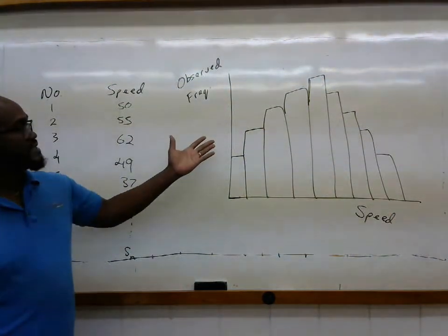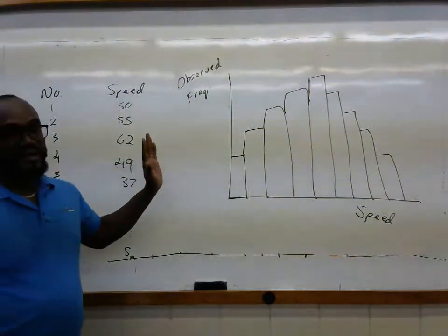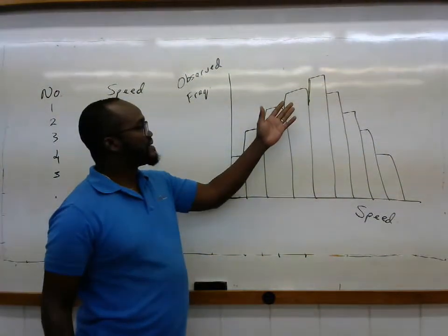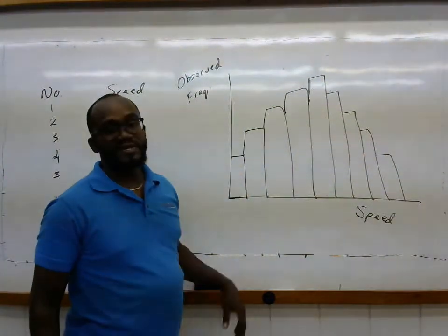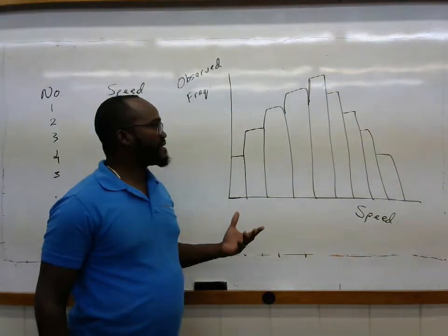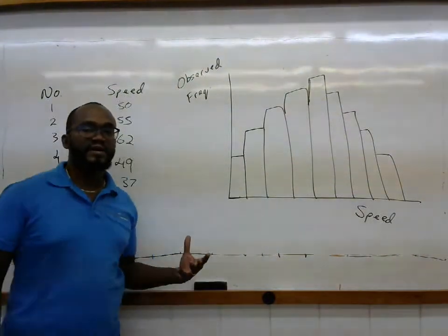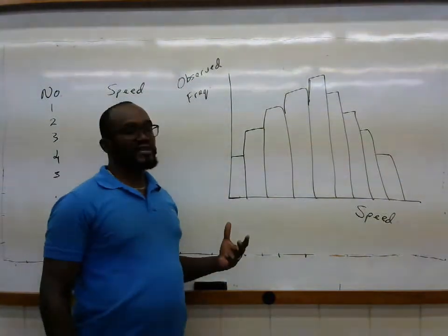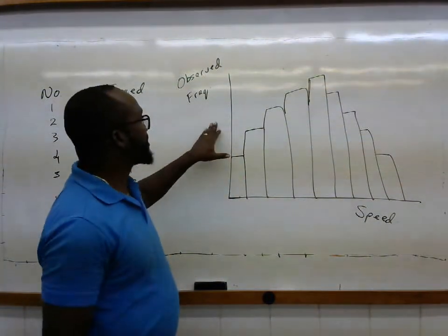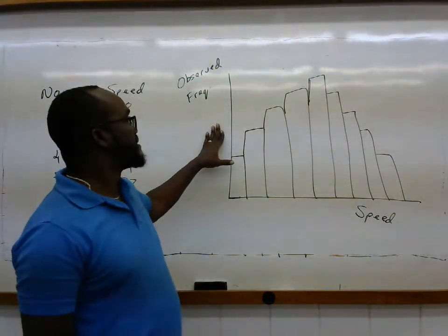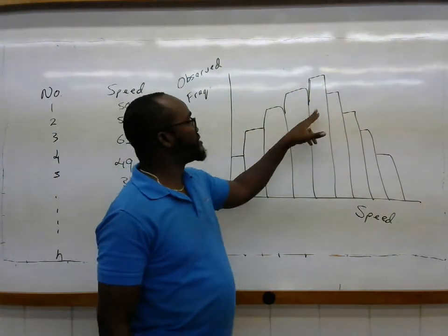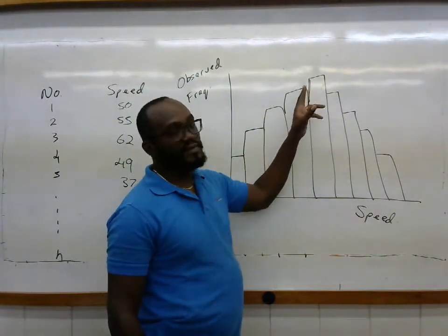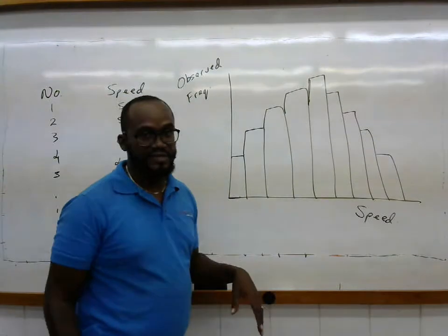Now, why is this important? Well, readily from the graphic, we can determine what the modal speed is, which is, again, a very important statistic when we're looking at speed data across different facilities and what drivers are actually doing. So the first chart we're going to generate from the data is a frequency distribution chart where we can determine the modal value for our speeds.